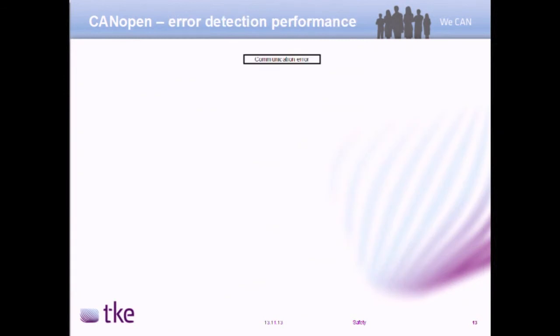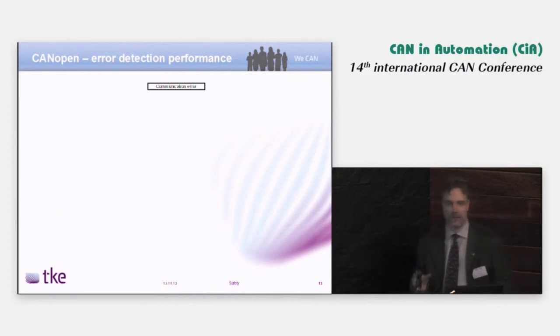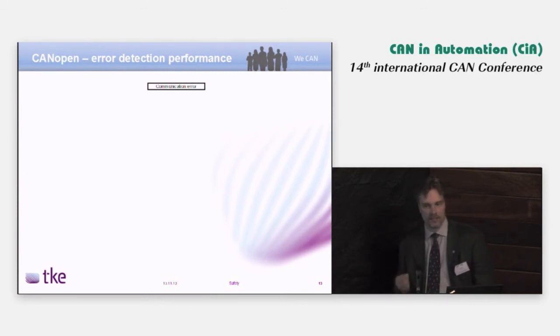And in the first stage, to understand this problem, because the earlier analyses were more or less analyzing CRC performance and forgetting fixed fields and fields affecting the DLC and other stuff. And in each analysis, those people have forgotten the CANopen application layer. They were analyzing CANopen networks just as CAN layer networks without CANopen safeguards.